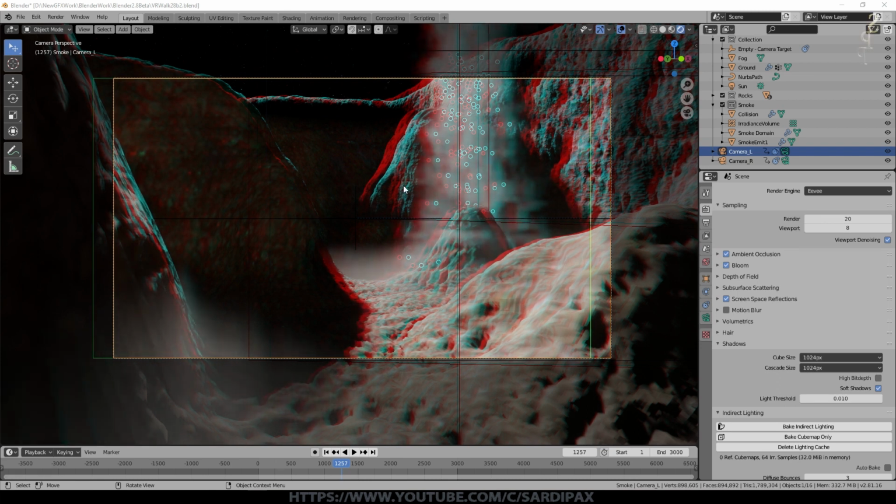I'm in preview mode, and this is all about Eevee, by the way. If this was in Cycles, some of the things would be slightly different. You can actually do slightly more with Cycles than you currently can with Eevee. But you can see we've got a sort of greenish box here, which is the left-hand camera, and then there's a reddish box that you can't quite see because it's sort of yellow at the moment. It's the selected box, and that's showing your left and right camera.